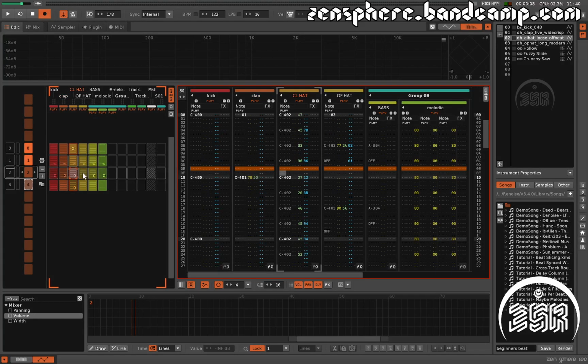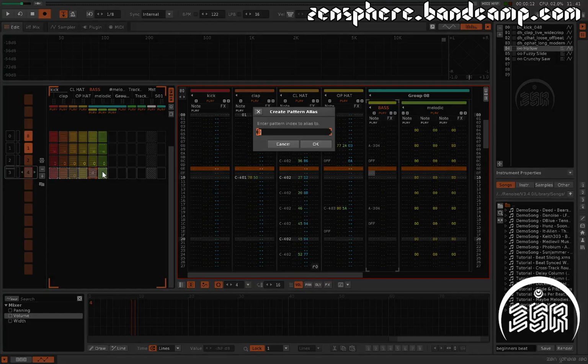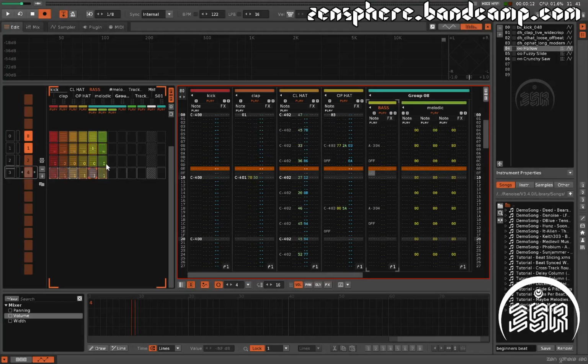And the reason the 0 comes up is each of these is showing where the alias originator is, right? Does that make sense? So we click on this pattern, it says, hey, I'm not actually this pattern, I'm actually this pattern. And that's letting you know. And then we could do this and do Command P once again, hit 1, hit enter, and oops.